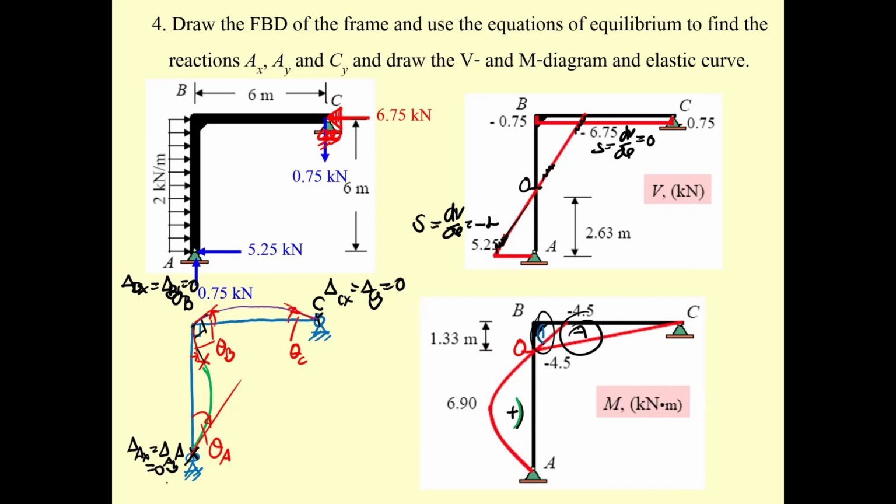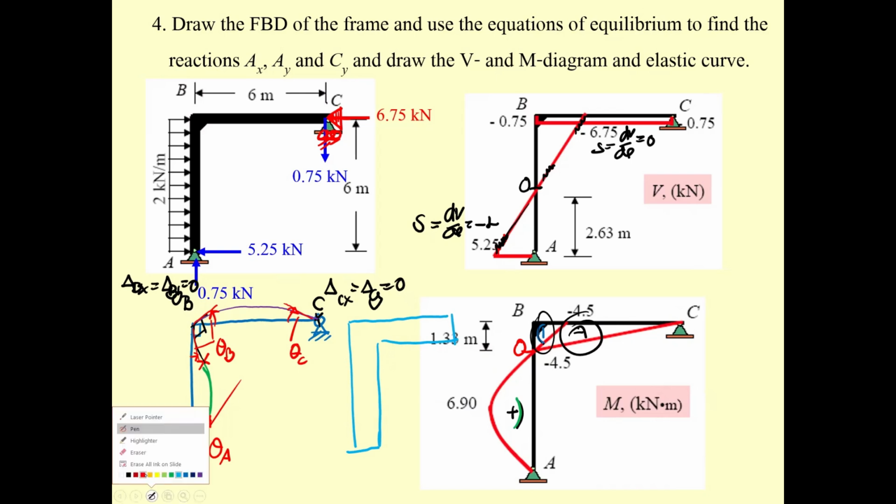Another thing, you should be able to draw the reinforcement for the frame. I always say that most of the time we run the steel along the length of the structure and hook it, in order to have a way to tie the stirrup.